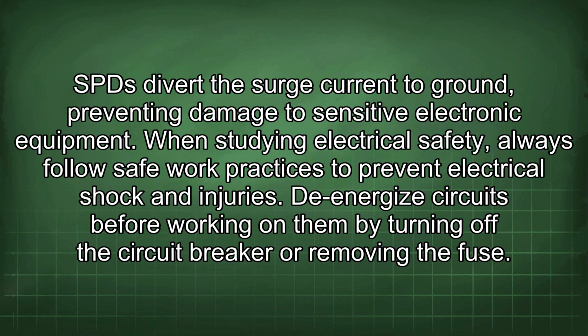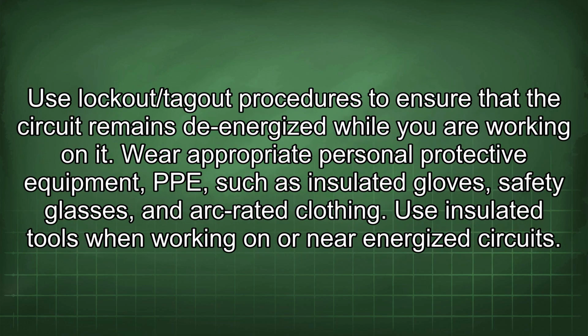When studying electrical safety, always follow safe work practices to prevent electrical shock and injuries. De-energize circuits before working on them by turning off the circuit breaker or removing the fuse. Use lockout/tagout procedures to ensure that the circuit remains de-energized while you are working on it. Wear appropriate personal protective equipment, PPE, such as insulated gloves, safety glasses, and arc-rated clothing.